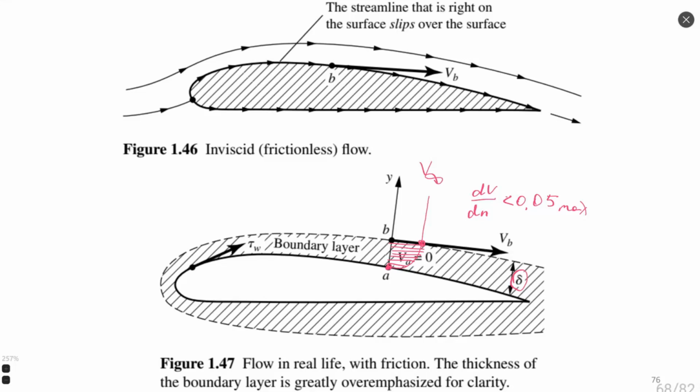Why am I saying boundary layer is so important? Because, for example, for simulation, ANSYS is using two different models to simulate flow. Inside the boundary layer, it uses the boundary layer model with viscosity, and outside of the boundary layer, it uses just inviscid fluid. The program automatically decides if some calculation point is inside or outside. So it chooses between two different models.